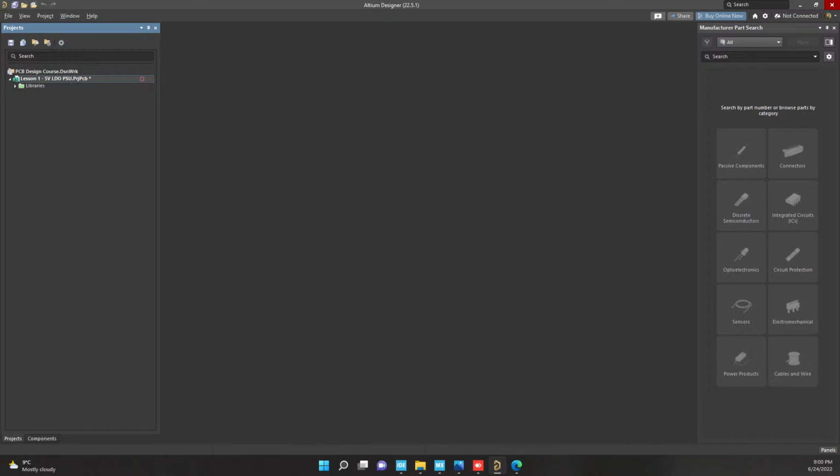Now, because you can see now that we added the library for the project, we have a library folder there with a compiled library. Okay, great. Remember, this star sign here shows us that this is not saved, so we can save it. Great. If we close our Altium now and reopen it, you will see that Altium will remember all of this now. All right. Now let's go on and add a schematic.